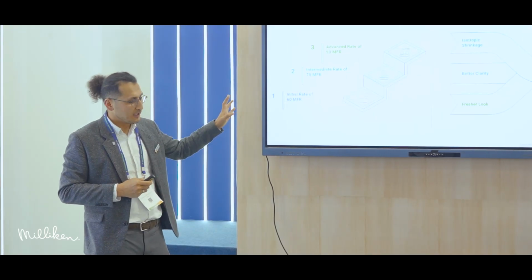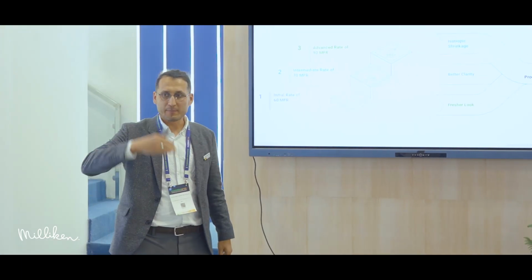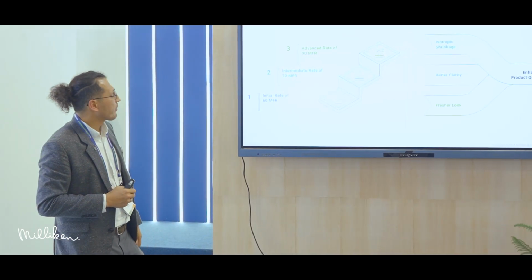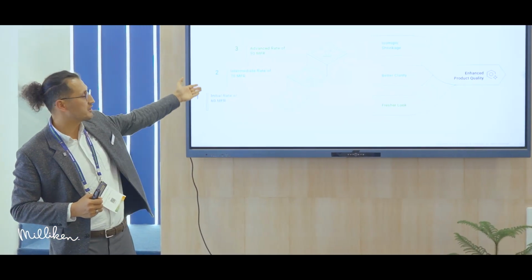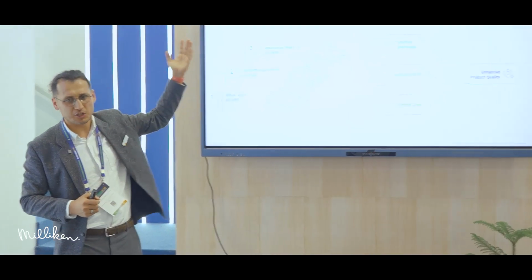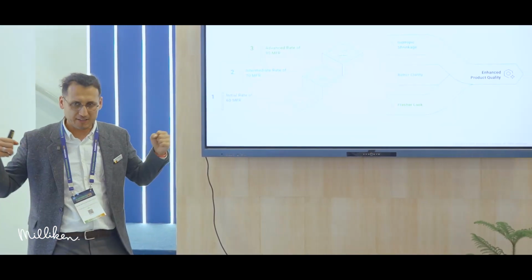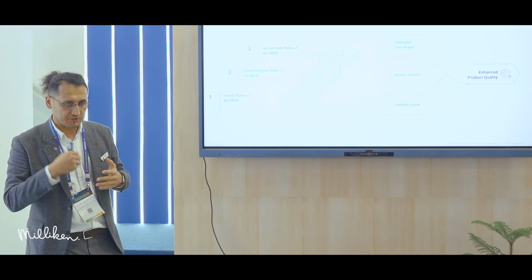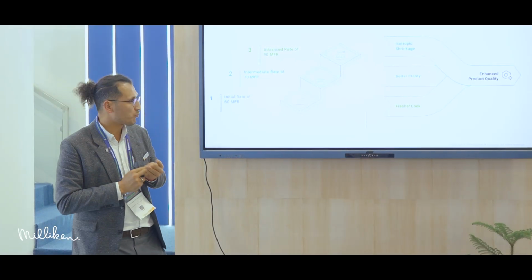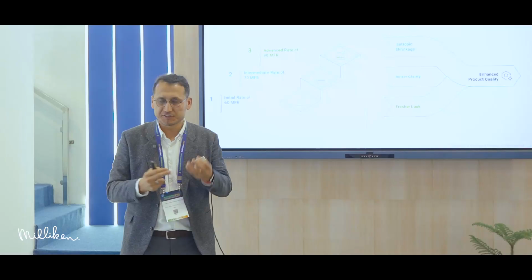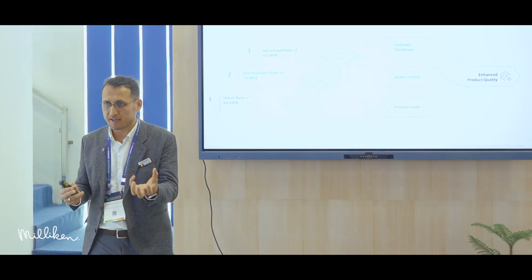And that is going to high melt flow homo PP. We are seeing from 60 going to 70, going to 90 and plus, even 100 MFR, to get more and more speed, more and more faster cycle time. And isotropic shrinkage is definitely the key. Clarity is important because customers want to see what's inside.